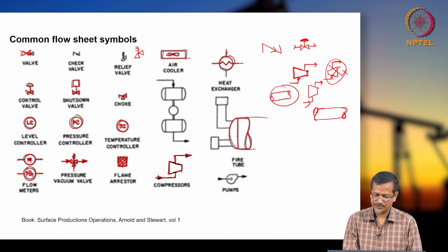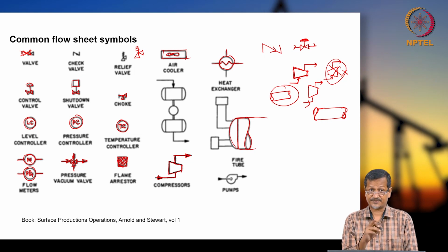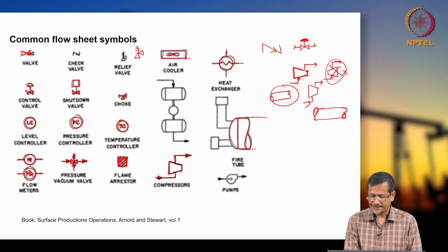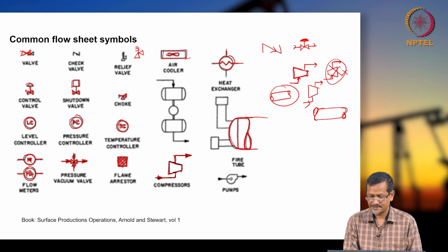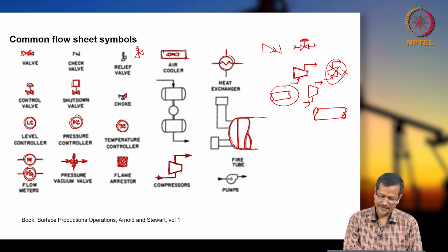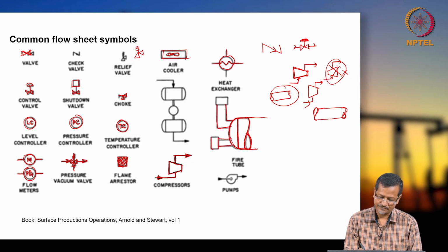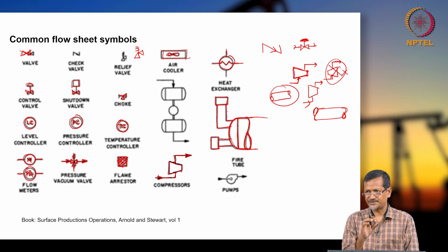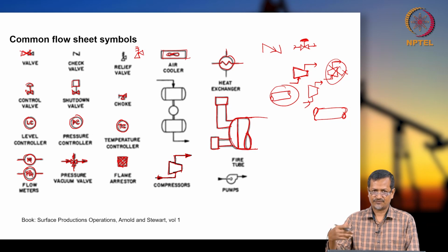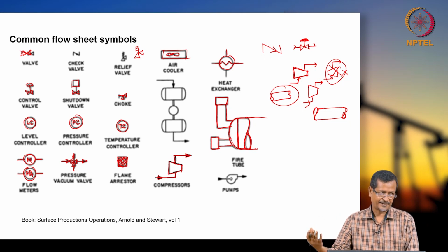And here the separator also, like a pressure vessel. Separator is a pressure vessel. I already told you, right? So the separator is like this, and you are cutting like this, and one line here, and this is the fire tube. So you are giving high temperature gas, and you are changing the fluid viscosity inside the separator.